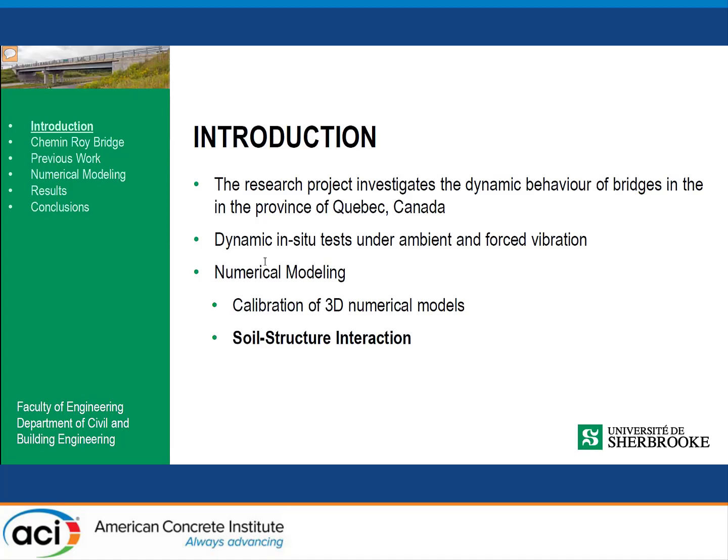Then in this second phase, we compared the superstructure displacement and base shears obtained with this rigid foundation model to two simplified methods. The first one is proposed in the 2014 edition of the Canadian Highway Bridge Design Code. Like Mohamed presented, this is a simplified method without damping.